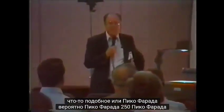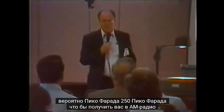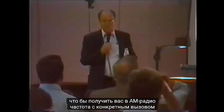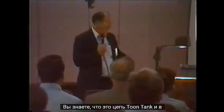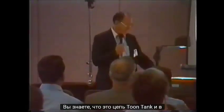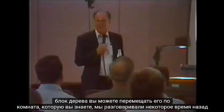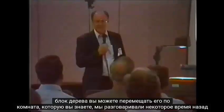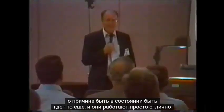It's probably picofarads. 250 picofarads, which would get you into the AM radio frequency with that particular coil winding. Yeah, it's a tuned tank circuit, and the other one, the second one there, is on a block of wood. You can move it around the room. We were talking a while ago about the coils being able to be somewhere else, and they work just fine.